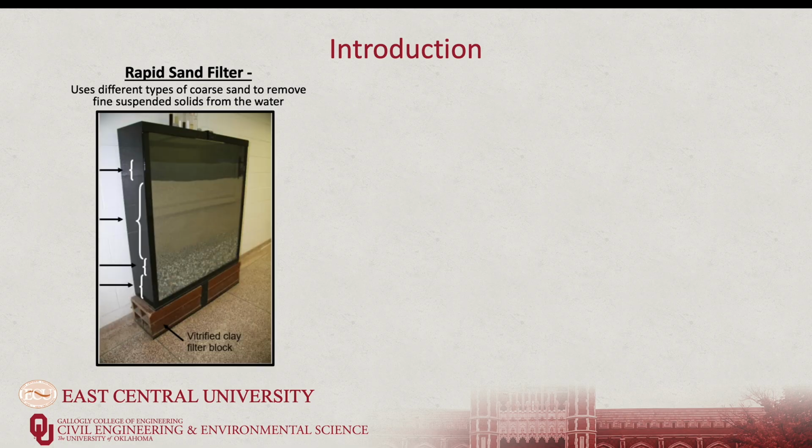In this image here is a rapid sand filter column filled with various types of sand media. Each media type has a different purpose for filtering water. For our top layer, we have coal, which helps with removing suspended solids and backwashing or cleaning your system. This is followed by a large volume of sand, which can remove fine particles suspended in solution, followed by a support layer of small gravel and large rock, which helps remove larger particles.